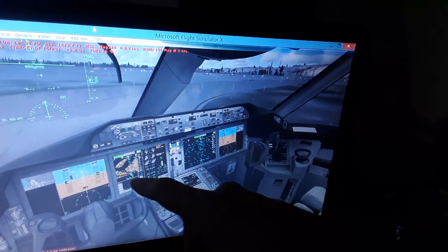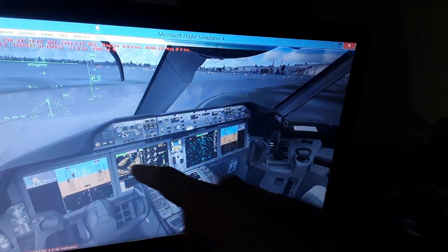We're gonna be having to fly with some waypoints in this flight. As we're gonna select here from the flight management computer, we're gonna have the flight plan later displayed with a purple or magenta line. And this is gonna be the flight plan the autopilot and flight director system panel is gonna follow. We connect the LNAV and the VNAV, the lateral navigation and the vertical navigation of the aircraft, that takes the information of the flight plan from the flight management computer.